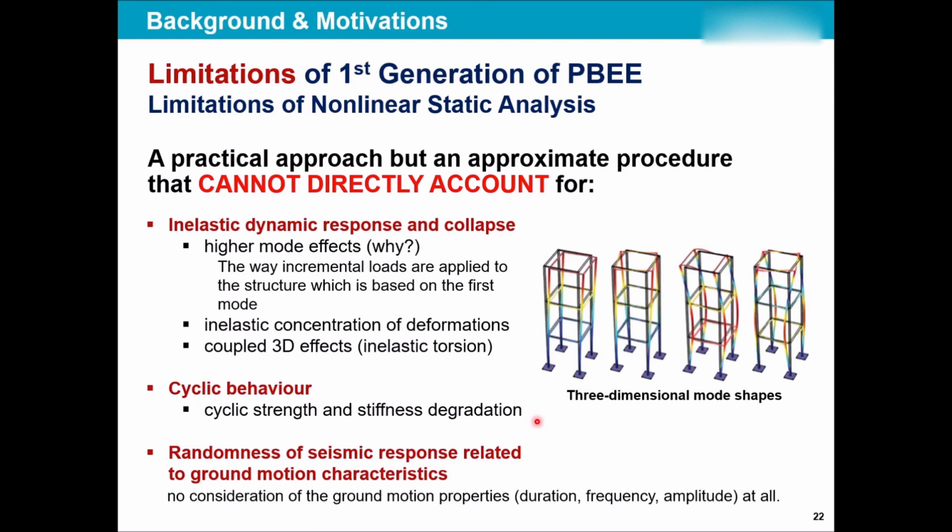And so far, we haven't gotten into the details of the ground motion characteristics. It was just simply the occurrence of the earthquake based on the response spectrums that we had in the code from before. There wasn't any PSHA, there wasn't any specific calculation of the hazard that we are dealing with. So all of these, with the points that we discussed in the previous slide, gathered together and really question the first generation of PBEE, because you don't want to go back and cause more problems. You want to be progressive and solve problems and come up with solutions.